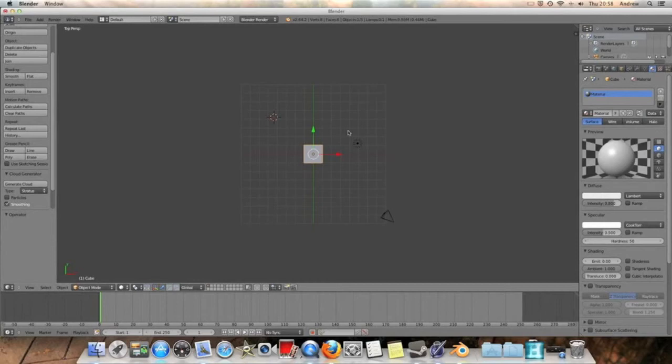But then we've got all these buttons in between, so I'm going to go to the front view and then I'm going to press 2, and that will slowly take us, I think it's 10 degrees probably, vertically around. And you know, I've never actually used that, but obviously it can be quite useful sometimes. 4 will take you horizontally around 10 degrees until you're back to where you started if you keep pressing it. And then 6, if I skip 5 currently, 6 does the opposite to 4, 4 taking you one way, 6 taking you the other way, and 8 does the opposite to 2, because it takes you up, 2 takes you down.